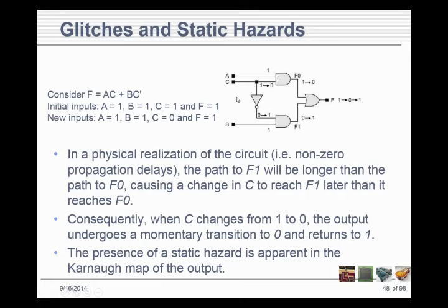But we got A is 1, that's fine. A is 1 here. C was 1 before. It went from a 1 to a 0. So the output here went from a 1 to a 0. Okay? So the output here, we've got to wait on that. Now this C was a 1, so that was a 0. But now this is a 0, so this is going to a 1. Everybody following that? Now these 2 1s are going to produce a 1 here.